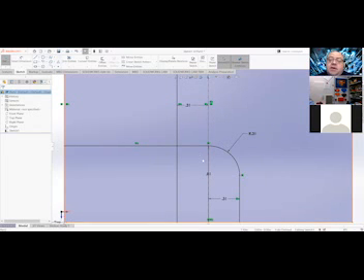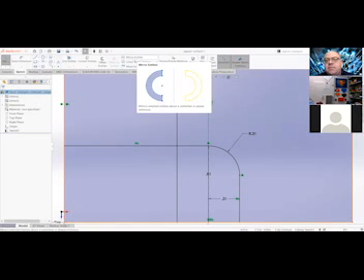So I'm using the elements that I've drawn and not adding, but I wanted you to know how to use the perimeter circle, and this is a good way to show you that. So I need this arc on this side. Let me show you two ways of doing that. One is a little more fun than the other. The one that's straightforward is a mirror.